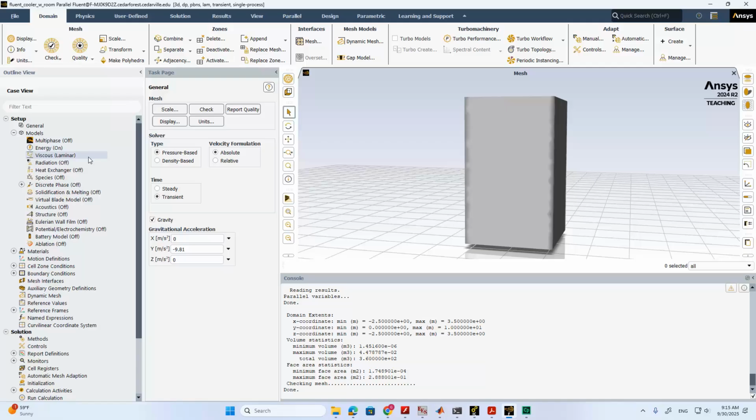When such a transition from laminar to turbulence occurs, it always occurs at a certain critical Rayleigh number. So you should first do some preliminary calculations to give a rough estimate of the range of the Rayleigh number in this whole process.